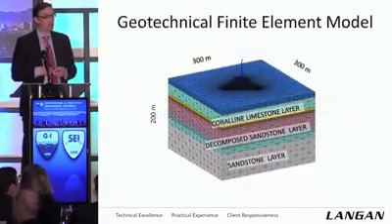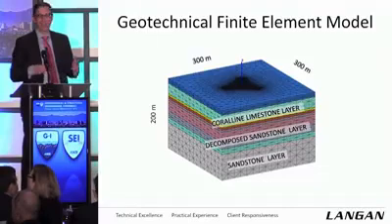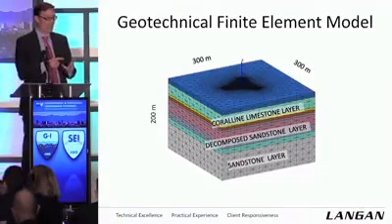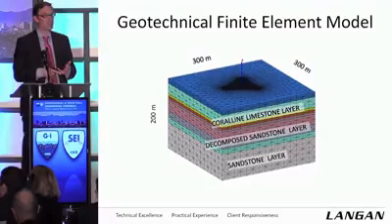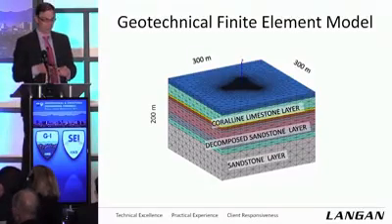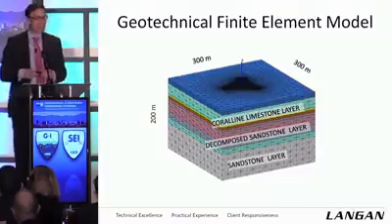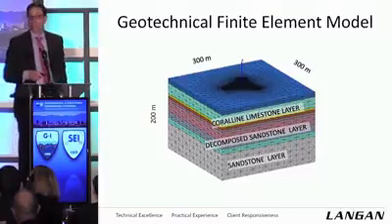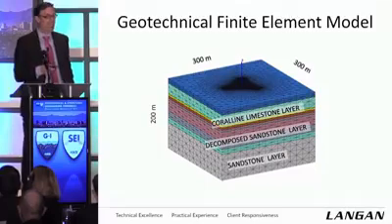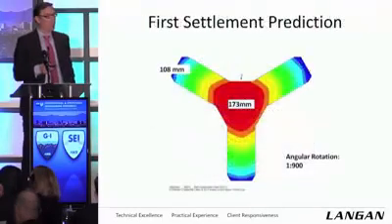So this is our finite element model, the idealized profile. We model the ground, obviously, the piles as embedded beams, and the raft as a plate with its appropriate thickness and stiffness. And then apply, as I said, the loads that Bob's team gave to us on the top of the raft.